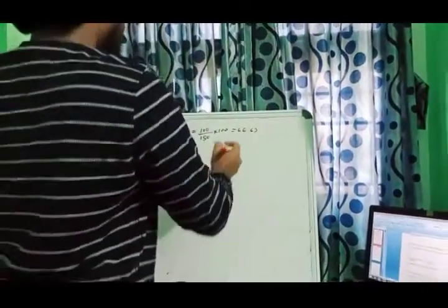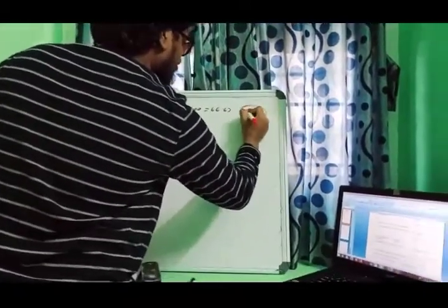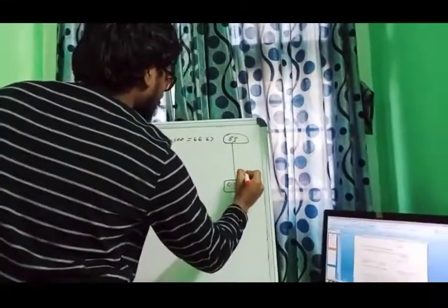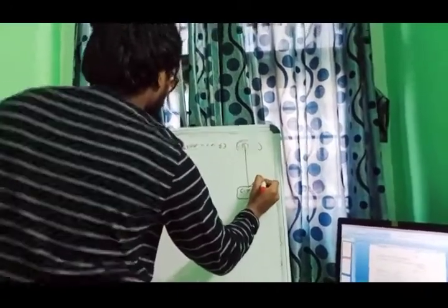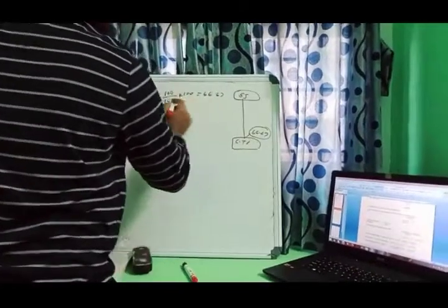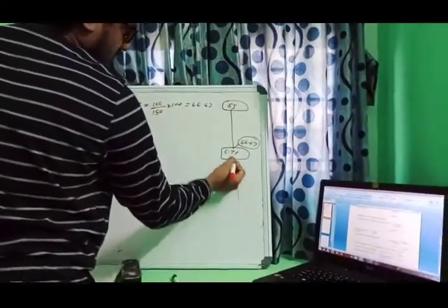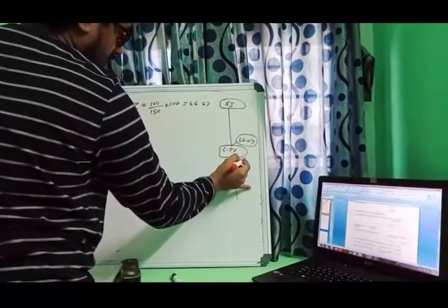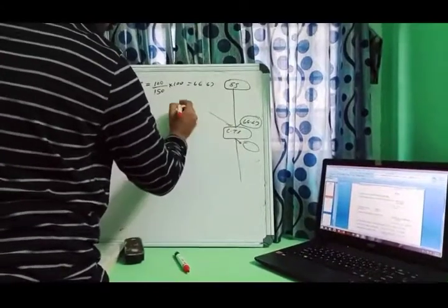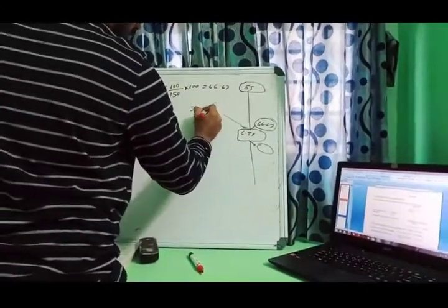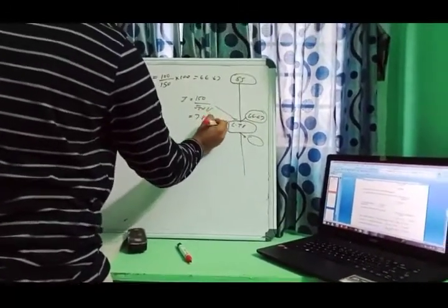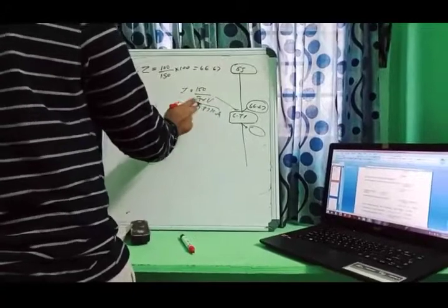Now this is the substation transformer and the consumer's transformer primary feeding point. Up to this point we have 66.67% as per the assumed value. Before finding the percentage impedance at the next point, we can find the fault current here, which is I equal to 150 MVA by root 3 into V, which comes around 7.87 kA. That is the fault current at this point. This will be used further for earthing calculations.